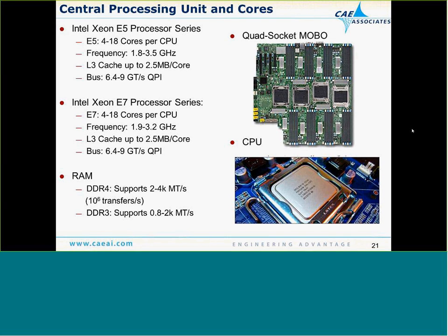It's also about how much information you can pass through the bandwidth of each chip, how fast it communicates to the RAM. So there becomes a point where that single pipe through your single CPU, the communication between the RAM and the chip, becomes saturated. And in general, what I have found through experience, with no hard rule of thumb, is that somewhere around 8 cores is the optimal setting for your bandwidth per chip. So you want dual or quad socket boards with 8-core chips. Now, if Intel and company increase their bandwidth, of course that'll change as technology improves.